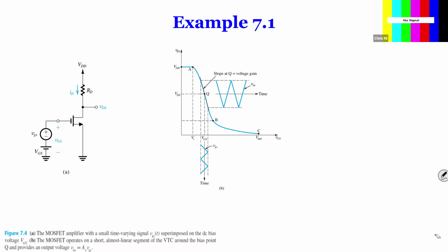If you plot VO as a function of VGS, so this little VGS over here is the input, and the VO is over here, and we call it VDS here. If you plot the relations, you'll find a curve like this. Apparently, if we bias the point, the capital VGS, in the middle, that's the best because you have your maximum swing of output or input.